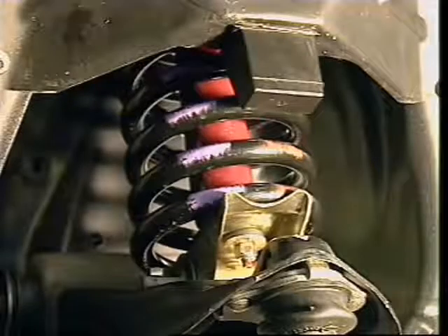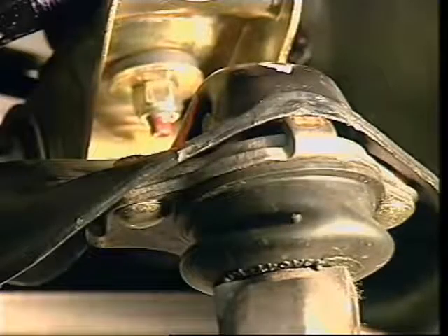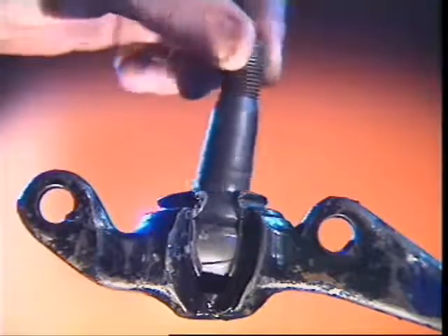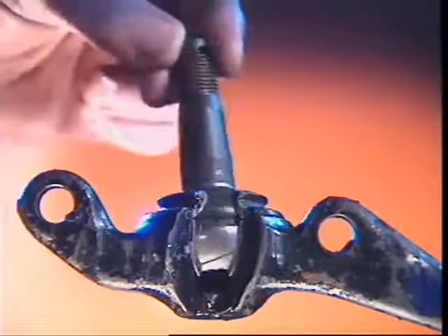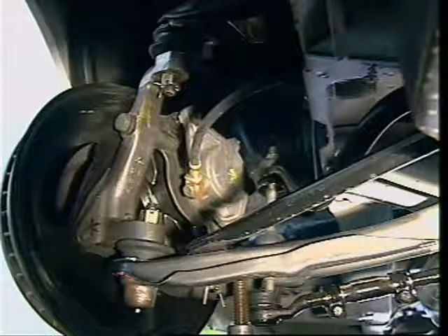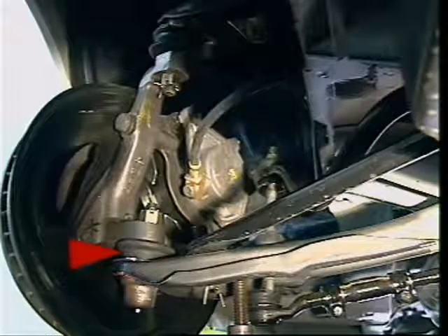The ball joint can be a sealed, self-contained unit fastened to the control arm in a number of ways. It is made up of a pressed steel housing, fitted with sintered iron seats and a hardened ball stud. A taper on the stud locates in a mating taper on the suspension unit, and a rubber seal keeps out dirt and water.